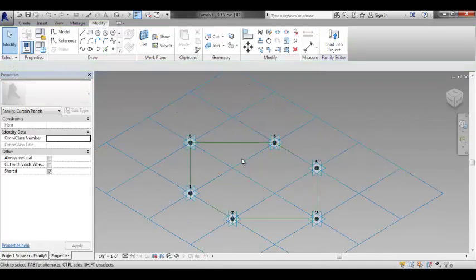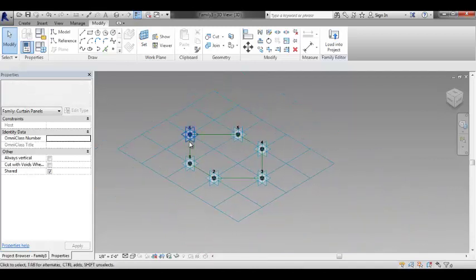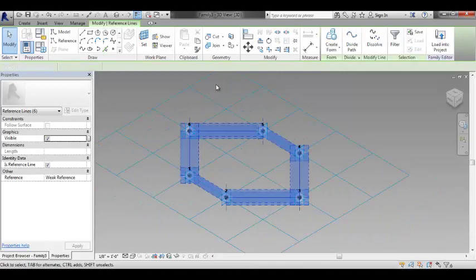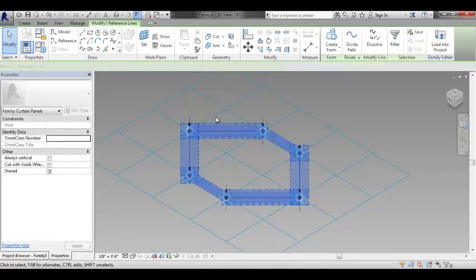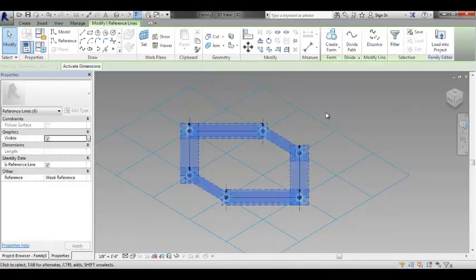Okay, so on this one I want to create kind of like a starred pattern on it, right? So I think this one's online somewhere. But basically I'm going to elevate it so it's got kind of this quality that's kind of geodesic, diamond-like kind of feel to it. So I need to use my lines to begin building other geometry. So I'm not using reference planes anymore in this type family. I'm not using planes, I'm using reference lines.